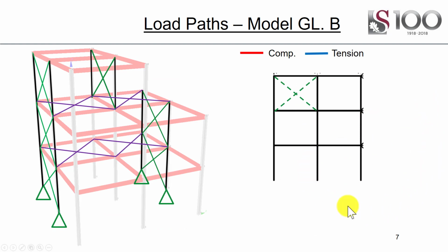I'm going to start on grid line B, so that's this middle bay. Let's have a look now. Which loads are we going to apply? Well, I'm going to be designing primarily this top section, but in reality, it's this whole bay. And so I want to now support the structure, and I'm going to support it at level 2 and level 1 with the floor bracing.